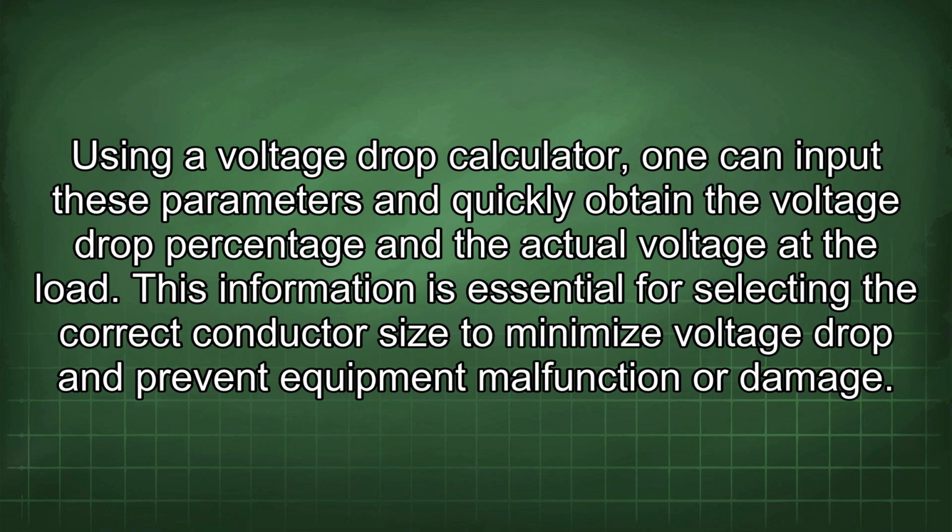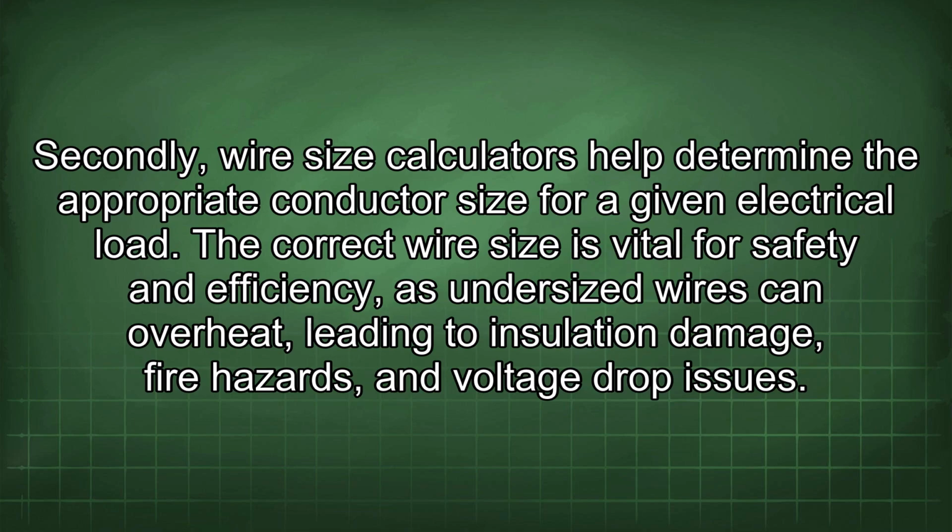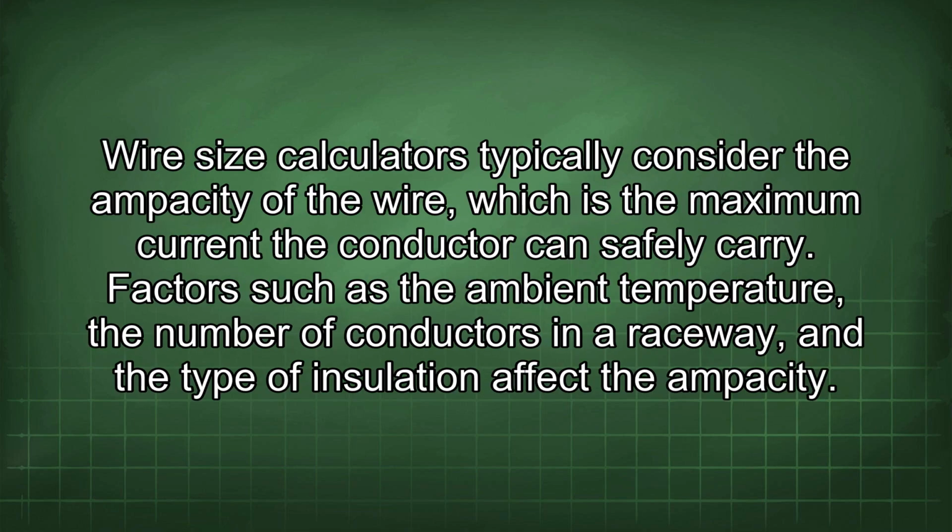equipment malfunction or damage. Secondly, wire size calculators help determine the appropriate conductor size for a given electrical load. The correct wire size is vital for safety and efficiency, as undersized wires can overheat, leading to insulation damage, fire hazards, and voltage drop issues. Wire size calculators typically consider the ampacity of the wire, which is the maximum current the conductor can safely carry.